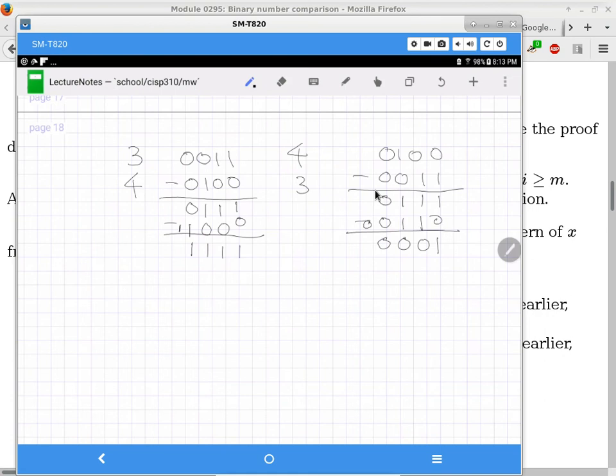Okay, so looking at these two examples, do we have a flag of some kind? Is there a single bit here that can tell us the ordering of the two numbers that we are subtracting? Yep. The carry. The borrow or the carry, exactly. They're usually called the same thing. Most people just call it the carry, but in a subtraction context, we can call it borrow as well. So the borrow flag is sufficient to tell you whether the minuend is less than the subtrahend.